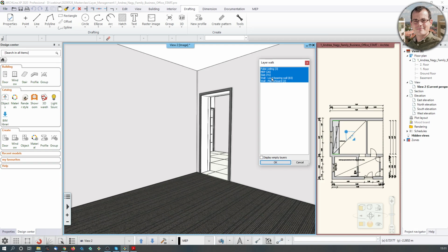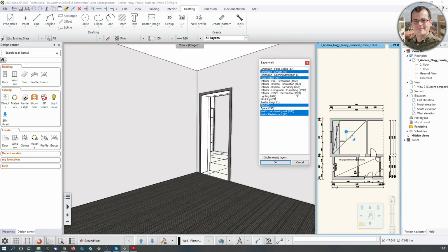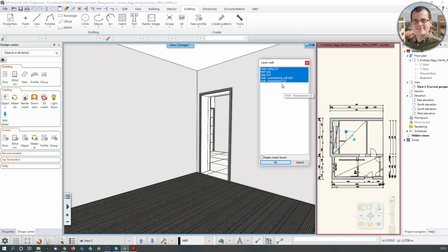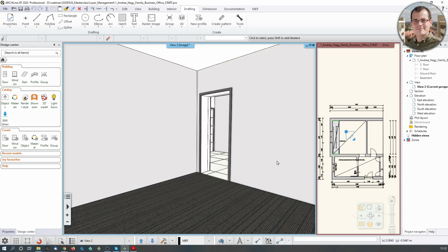They are actually separated, because the way you are pre-filtering the content here with the layer walk is what is going to be your layer setting in the 3D. So if I go back to the 3D and I go to the layer walk, I can keep on disabling things, right? But I can only disable things which are enabled in the 2D. So I can only switch on and off things in the 3D which are already on in the 2D. Hope that makes sense.